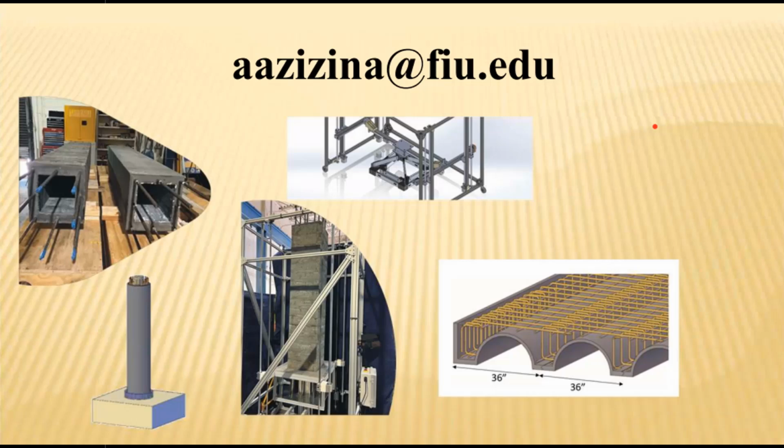Yeah, I think so. I think when we get to the point that we can feed the material that we need, and the nozzle moves at a constant speed, then you will get a completely smooth surface. The reason that right now we have a little bit of striation is that we were feeding the material by hand, and also we had to wait a little bit before we go to the next one.